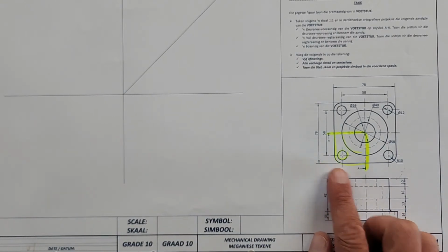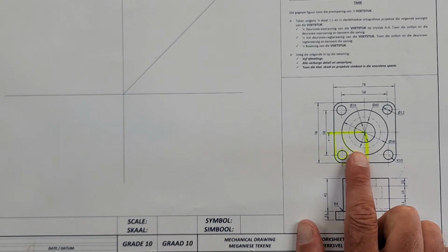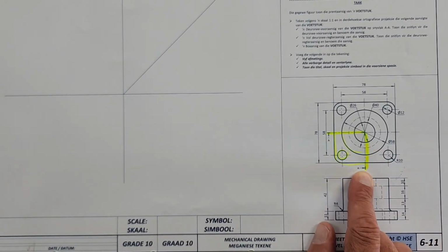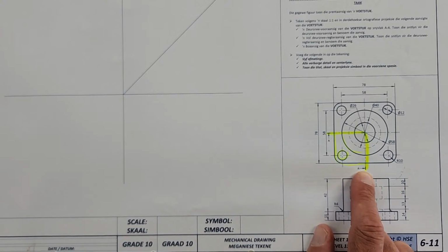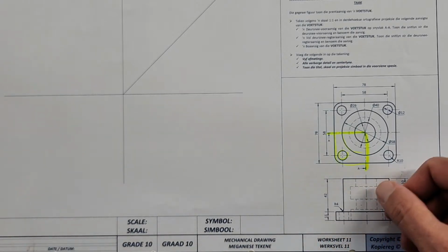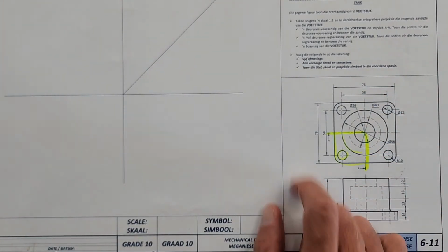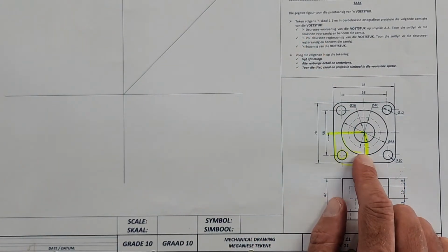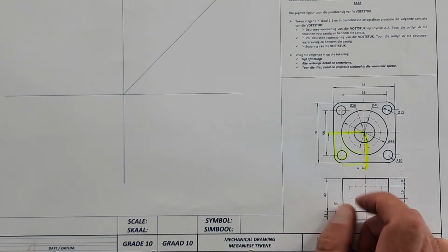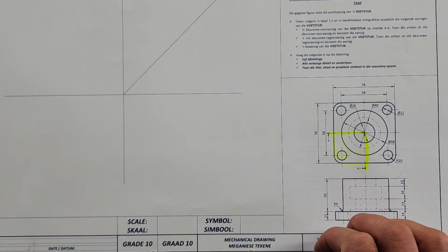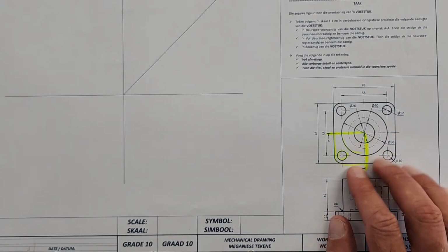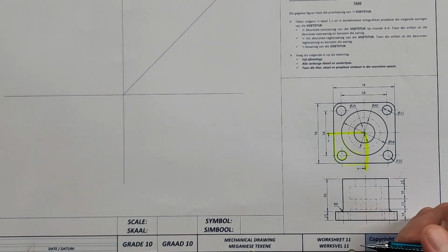All right. What we have to do, a sectional front view on cutting plane AA. There it is. Of the pedestal showing the section line for the sectional front view and name the view. A full sectional right view. So in the right view, it is going to be a full section. It says there full section right view, and show the section line, and then the top view of the pedestal plus some dimensions, all in detail, center line, show title, etc. Okay.